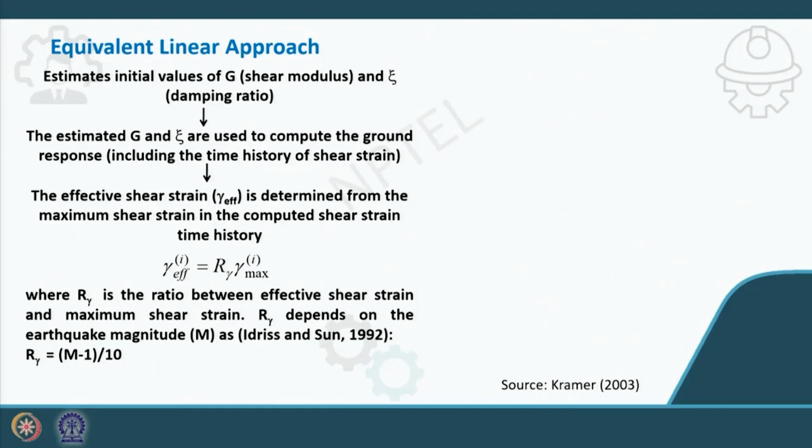So here, as I mentioned in the previous case, your shear modulus is not a function of time or strain. But actually the shear modulus changes with time, or as the seismic load increases, that means your shear strain will also increase, and the shear modulus value will change, or basically it will reduce.